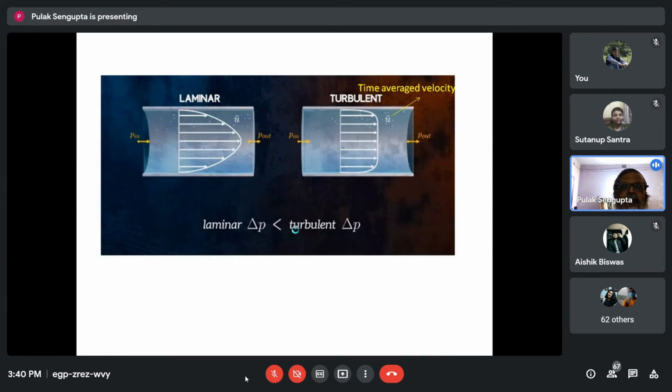These are the two differences. This is the particle path. You see the velocity change. You can see. So basically, what happens? It is through a pipe, and the reverse is not through a pipe. This upper part is air. But when fluid moves through a pipe, at this point, a thin layer will have no velocity because of the frictional force between the immediate layer and the wall of the pipe.